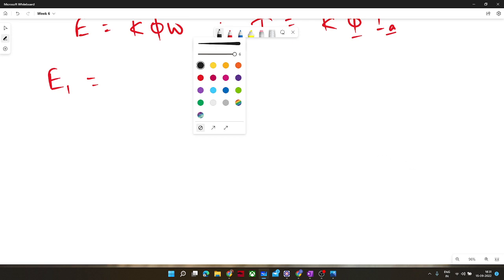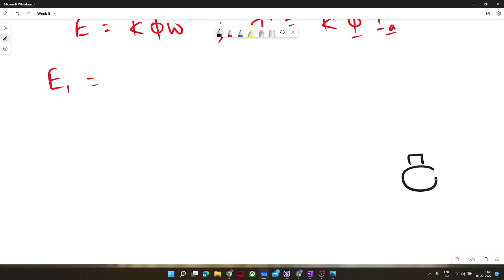I will explain it. Whenever we mention armature voltage, we mean how much voltage you are applying, right? You cannot apply the back EMF because this is a motor, so it will be developed. You are saying that I should call the back EMF the armature voltage, but that is not the case. I will explain why.